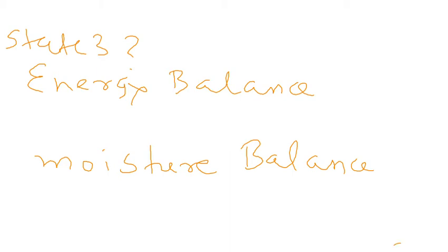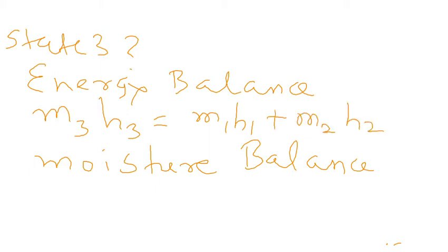Okay, so the energy balance is what? The energy balance would be M3 H3 is equal to M1 H1 plus M2 H2, where H is the enthalpy, and the moisture balance is what? M3 omega 3 is equal to M1 omega 1 plus M2 omega 2. Right? Understood?